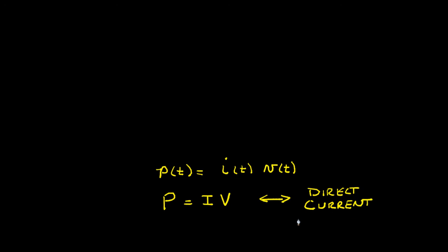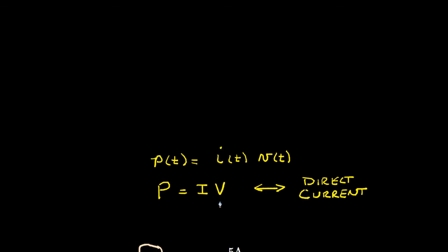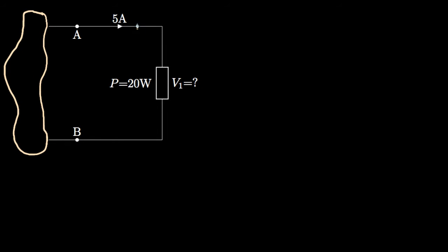Of course, for both of these equations, we need to be careful to apply the proper sign convention to distinguish between power sources and power sinks. Now, as an example, suppose we know that the current through an element is 5 amps and that the element absorbs 20 watts of power. We know it absorbs because the power has a positive sign. Now, if we use the proper sign convention, then the equation for the power associated with the element would need to know the polarity we're going to assign with our definition of this voltage. So let's begin by assigning the positive side there. In this case, this voltage tells us how much the voltage increases or decreases as we move from this side to that side of the element.